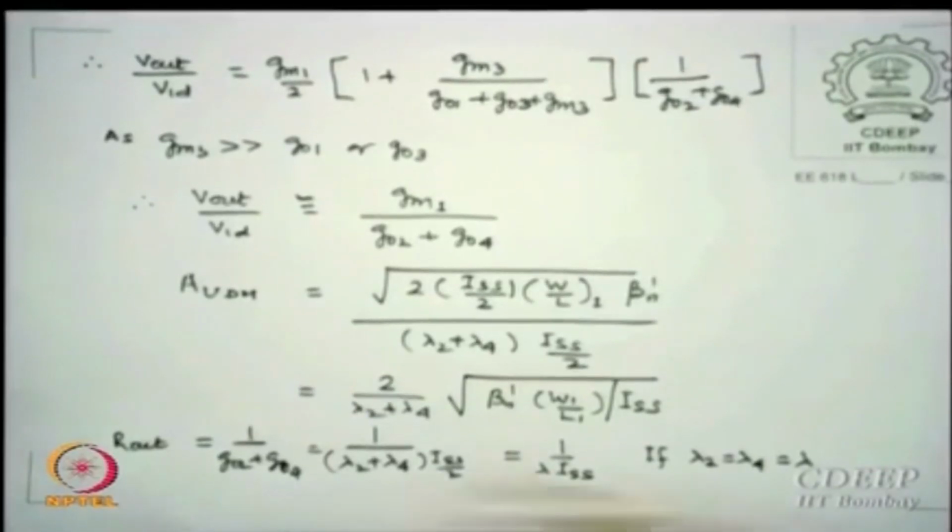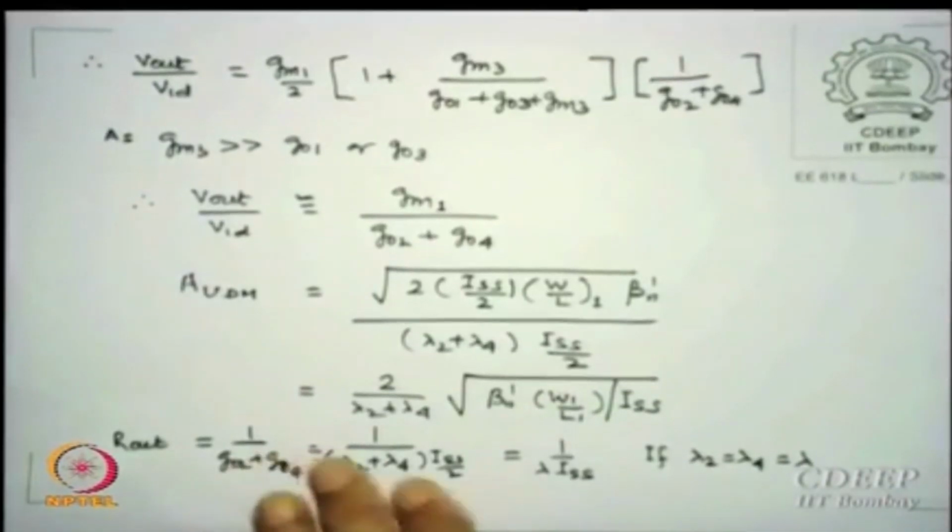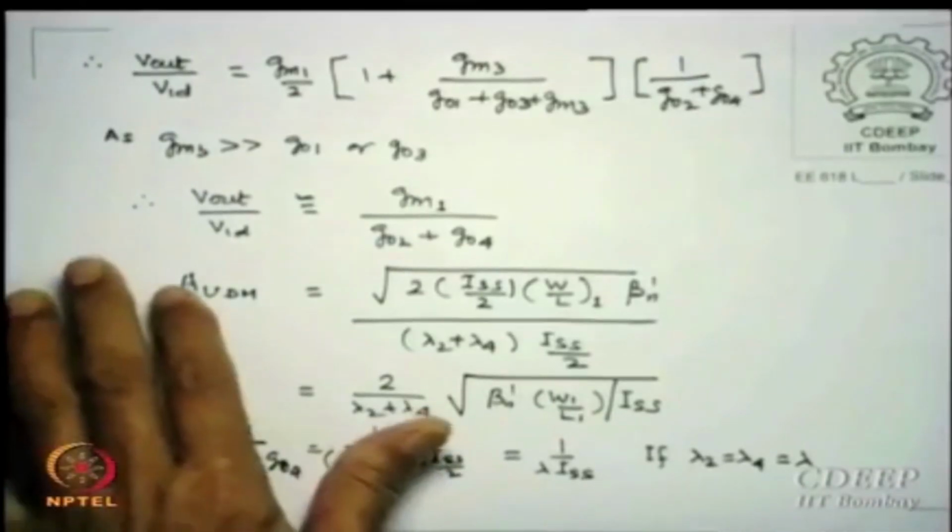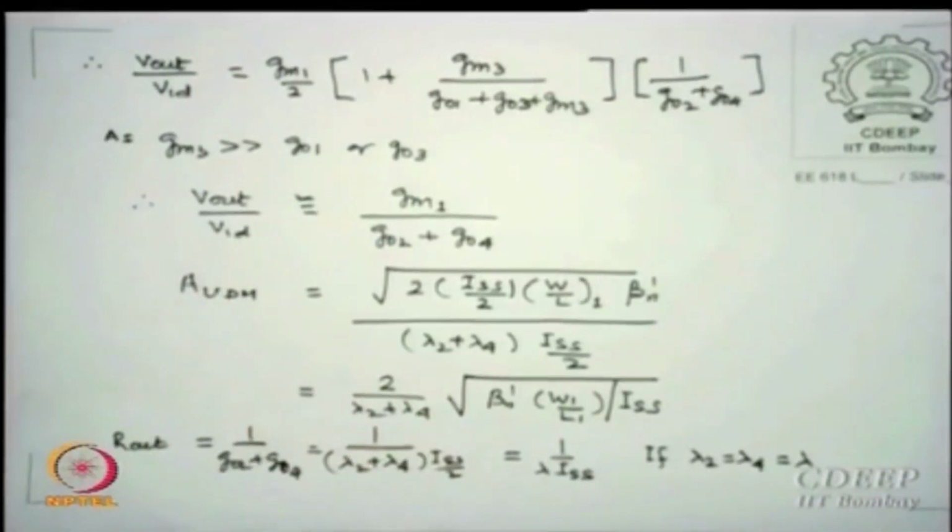Either by the transistor which I will put for the source ISS, either the size of that transistor or the bias of that transistor, or I mirror it from some other source which will give exactly the current which I wish. Okay, I will show you mirrored ones later when I calculate. So essentially I am trying to tell you that the designer can now relate, if you want so much gain, 10 to the power 4, 10 to the power whatever number you say.